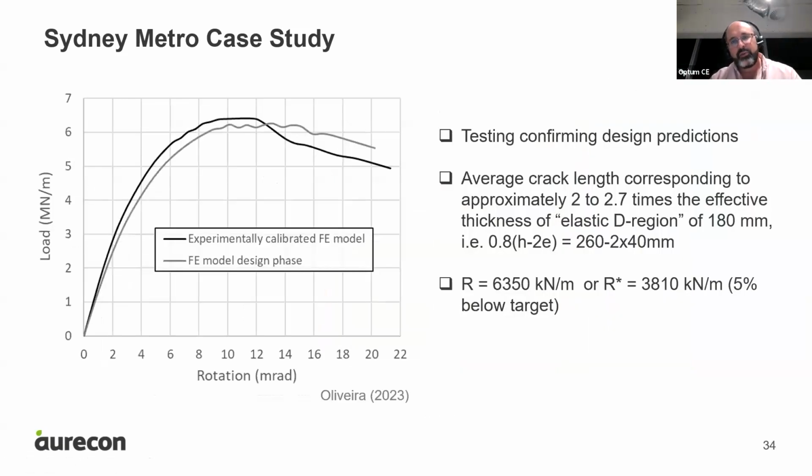And then we compared our predictions with what the testing results were giving us. And we were, again, demonstrating that the fiber reinforcement alone could provide the resistance that we originally thought was 5 times lower. The main difference is that instead of limiting the depth of the crack to about one segment depth or thickness, the crack had to develop much longer in the ultimate limit state. But by allowing that, and happening obviously with acceptable crack width, we could then develop the strength that we needed.